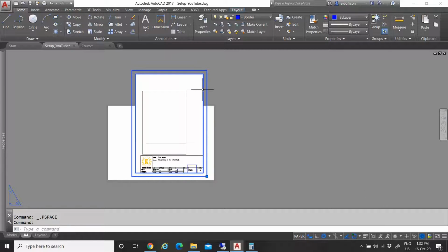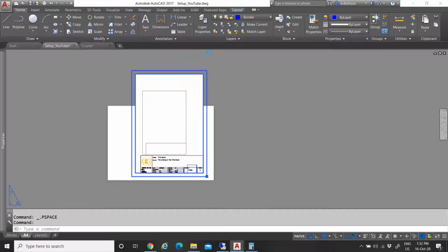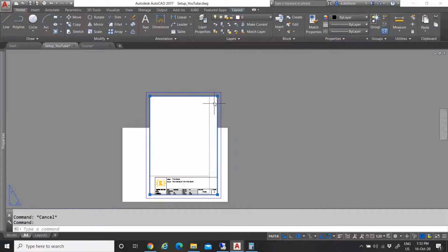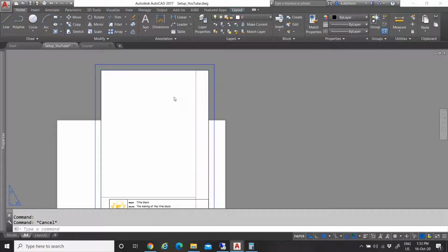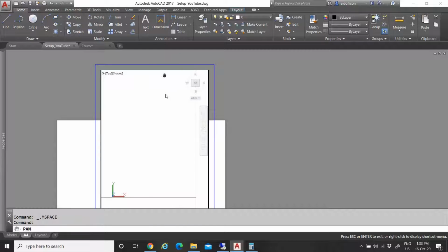This we have to send it to back. So our border will be sent to back, and select your viewport once more, and let's start at 1-on-20. As you can see, it's basically the same size as my help border that is on the inside.